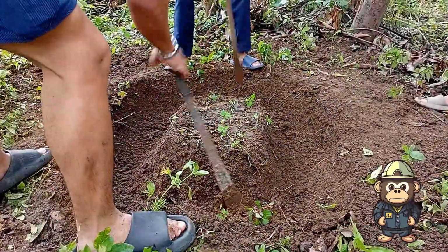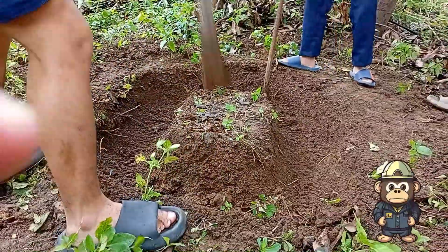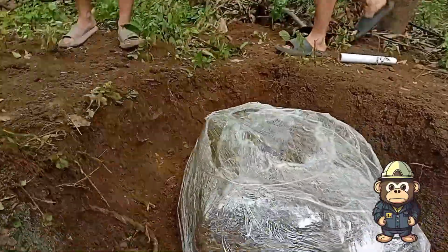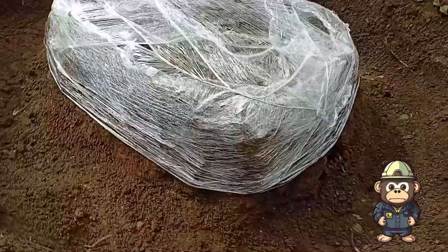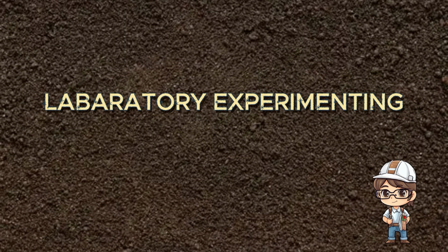For undisturbed soil sampling, after carefully extracting the soil sample using tools like a Shelby tube or core sampler, the sample is sealed tightly with cling wrap to preserve its natural structure and moisture. This prevents contamination and drying, keeping the sample in its original condition for testing. After collecting soil samples, we take it to the laboratory for experimenting.